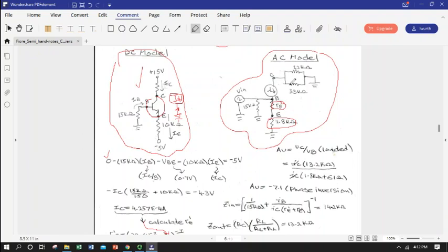So we can now define our gain in terms of the voltage at point C divided by the voltage at point B, and in order to define the voltage at the base, we of course needed r little e, because the collector current, which is similar to the emitter current in AC, just like DC, is going to flow from B to ground.